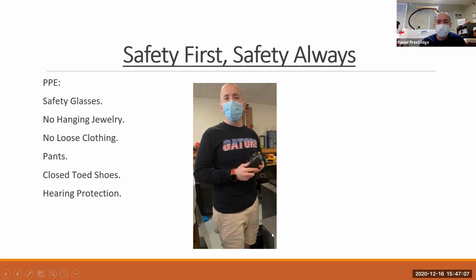But let's say that you kneel down, so you're cleaning or whatever, then the chips can get onto your knees and scratch you and get embedded. And that's always kind of a pain. We also want to wear safety glasses whenever we're cutting. So that would be kind of on the table. And then definitely have closed-toed shoes, which, yeah, it's kind of miserable getting those hot chips down near your toes and stuff.